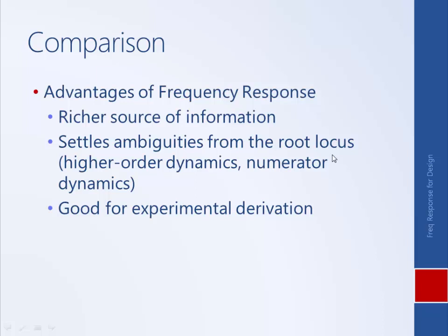Every time there's a pole, every time there's a zero, you can see exactly how the magnitude changes, how the phase changes, and in turn you see the effect on DC gain, gain crossover frequency, phase margin, all of these things that tell us about a system's time response.